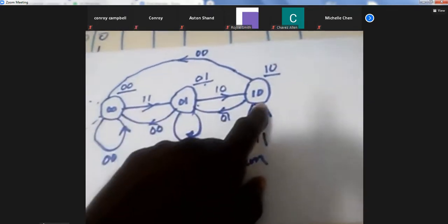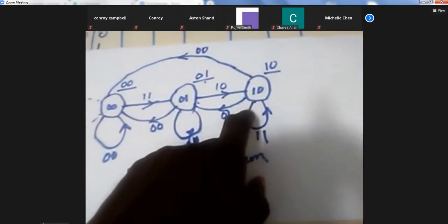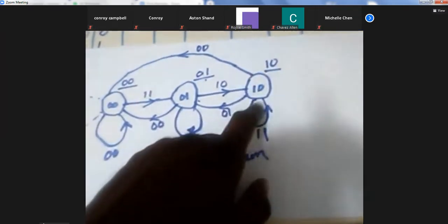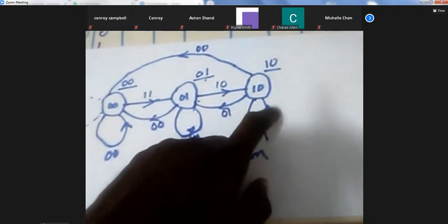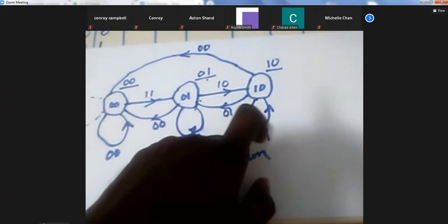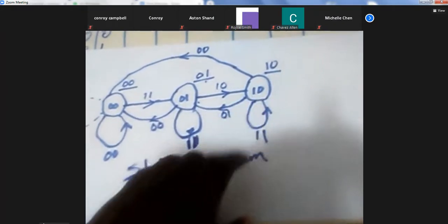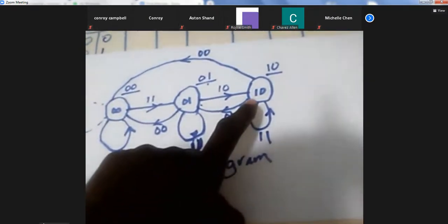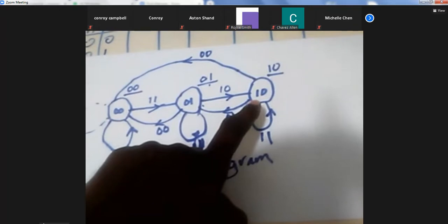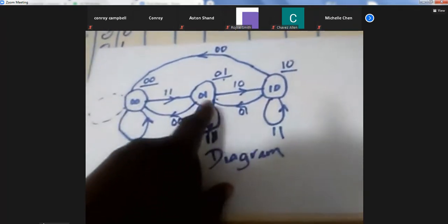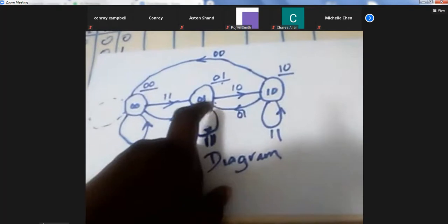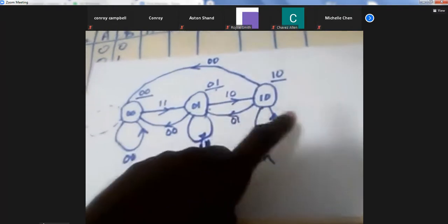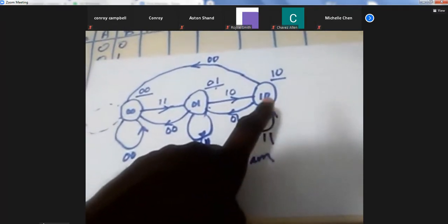All right. So the next one was if we press the start switch while the conveyor is running, then what your classmate said, and I agree with, is that it should just continue running. Yeah. And then 0, 1 was that if the Apple sensor goes off, then what is to happen is that it's going to start the box motor back, get another box, start another box. Okay, all right, yeah. And then we ignored the Apple sensor.